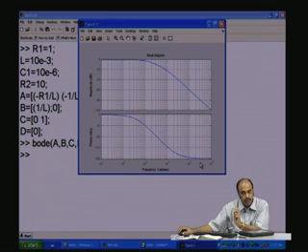So, two poles, each pole is going to add a 90 degrees phase shift. There are two poles and therefore, there will be 180 degrees phase shift, and each pole is going to add a slope of minus 20 dB per decade filtering action. There are two poles and therefore, there will be minus 40 dB per decade filtering action.